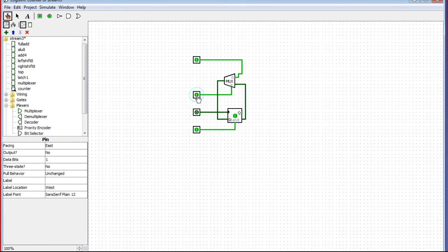If we turn the toggle mode on, this input doesn't matter, and the register, when you clock, it just flips its value. So we clock it, becomes 0. Clock it, becomes 1, 0, 1, 0. That's toggle mode. Load mode, toggle mode.